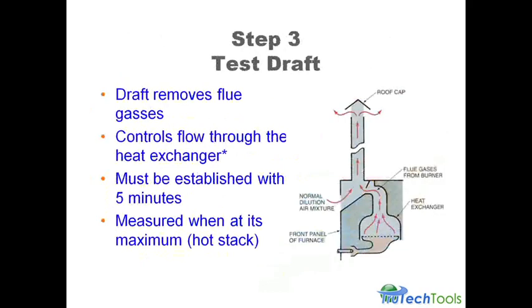Our draft test removes the flue gases, and draft controls the airflow through the heat exchanger. Now, I have that starred there because what I want you to realize is draft physically separates the appliance from the chimney. Okay, so this is really important on atmospheric draft appliances that you understand this.